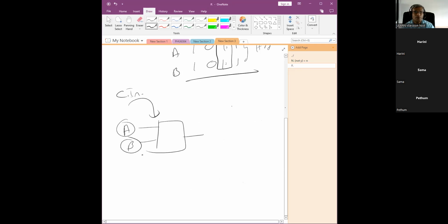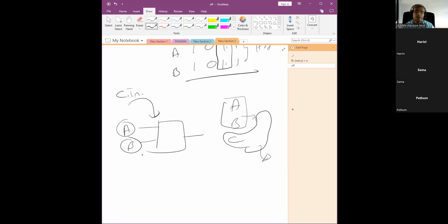If we are to, let's say, add 3 numbers, one thing we can do is first add these 2 numbers together, take the result, and then add these 2 together, the result and this one, and get the final result. So it's basically doing the addition two different times to get the final result. A circuit that is able to add 3 bits is called a full adder.